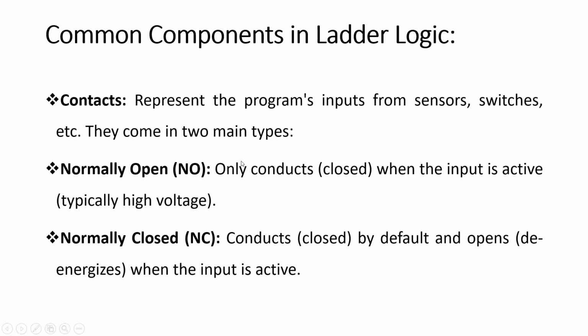So this normally open contact is actually not closed but open, so you have to first close it and then it is able to conduct. The normally closed contact, by default, is always closed and opens when you de-energize that kind of input.